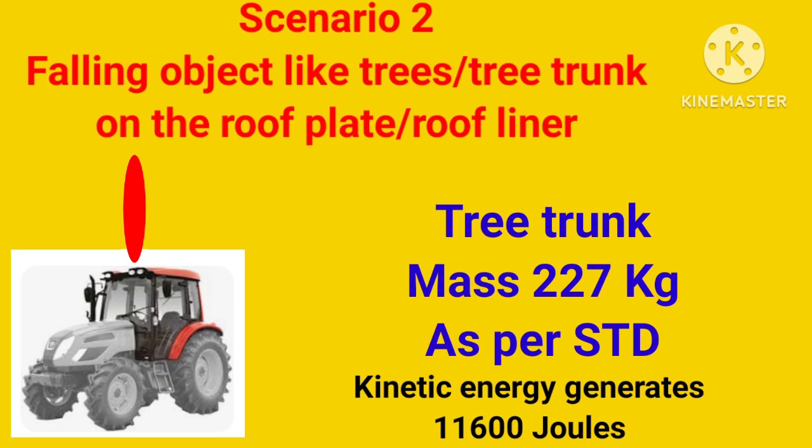So we need to conduct a trial to confirm that if such a case happens, then the roof plate or roof liner plate of an excavator, loader, backhoe, crane, or any heavy machine has to absorb that energy by using ductile material, that is, the Charpy V-notch material test.